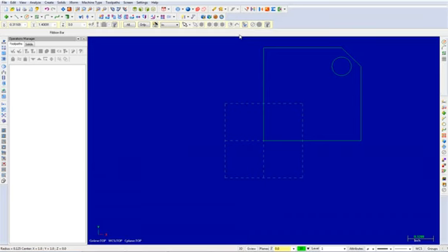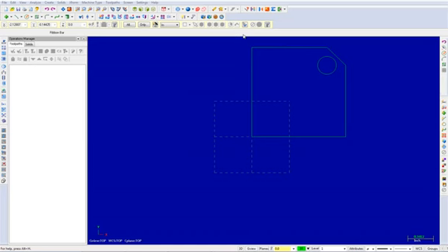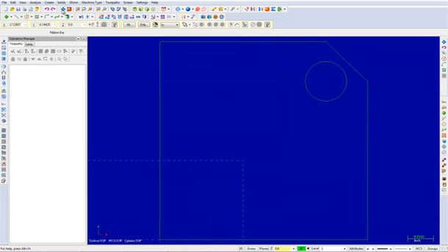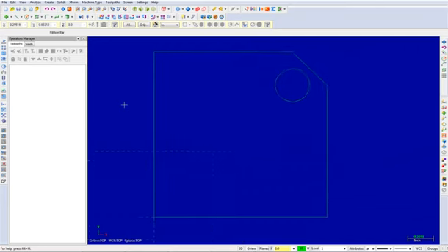Next, we will create polar arcs. In this step, you will create two polar arcs knowing the radius, the center point, the start angle, and the end angle. Select the Fit icon. To zoom out on your part, use the mouse wheel.